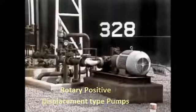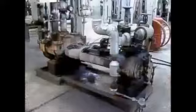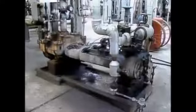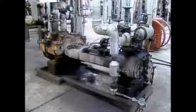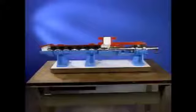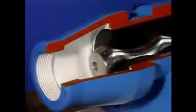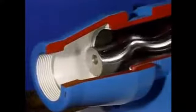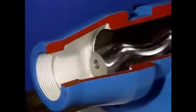Pumps used to keep liquids flowing through plant piping are positive displacement pumps. They use different types of internal components to push or positively displace controlled amounts of liquid through the pump. One type of positive displacement pump that's commonly used in industrial plants is a rotary pump. Rotary pumps use the rotating motion of components like screws, gears, and vanes to move process liquid.